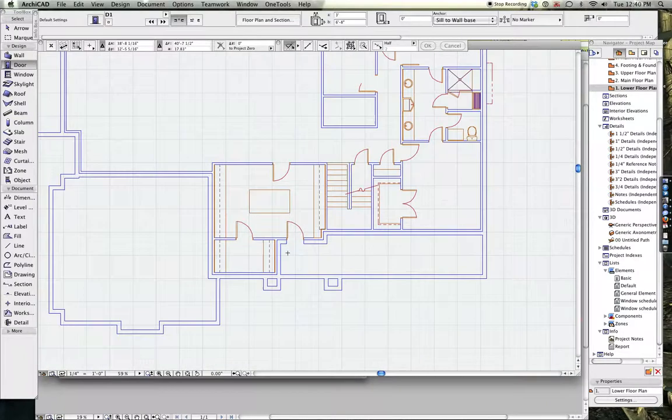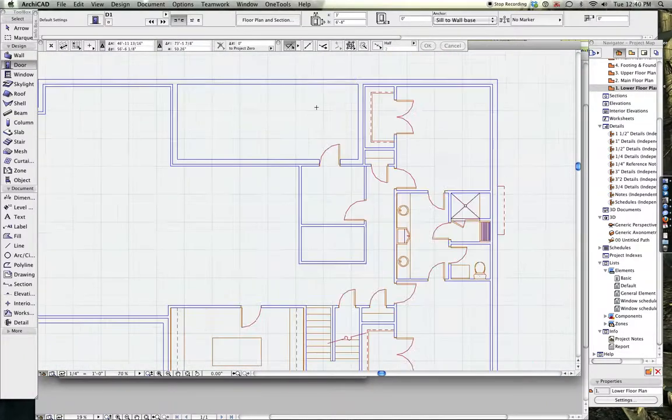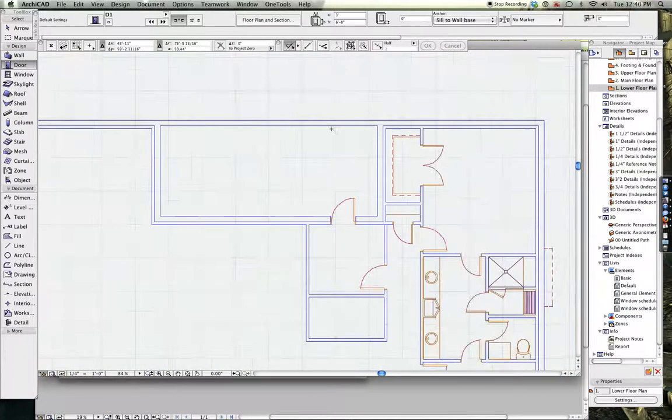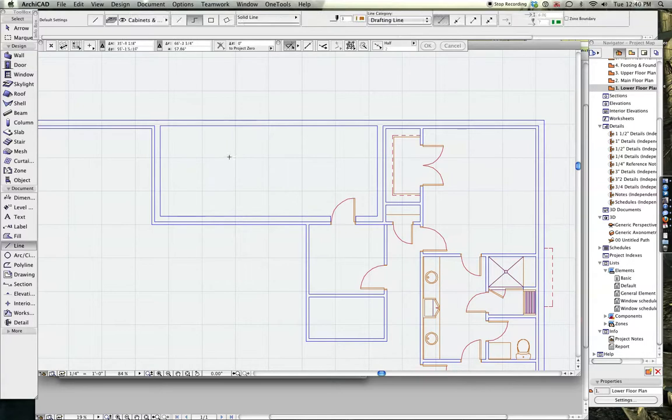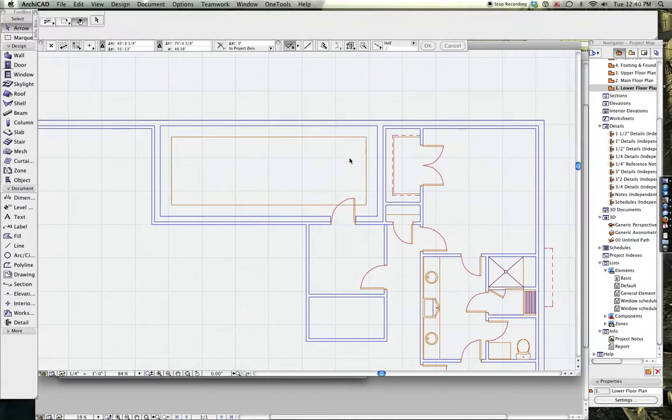Like that. Okay. And then in here we'll have storage, so we can hit the number 4 key on the cabinets tool, 3, then we're going to offset it. Then we'll put 16-inch shelves in, so we held down the space bar to space click in, we hit the E key for the offset, and then we type R to invoke the distance, and type 1-4, and that puts that in there.